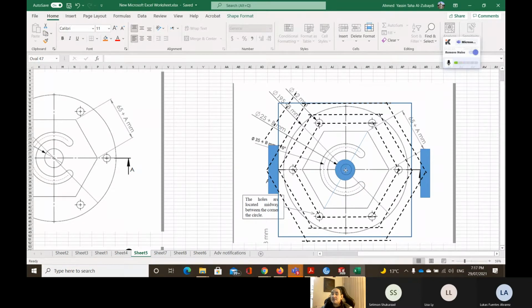Travel with G00 to X0, Y0, and Z equal to 5. Then you go G01 to the depth of the slot. We are going to be in the middle. Then we turn to the side where the center of my cutting tool will be on this circle. Then we make a 180-degree cut, and another 180-degree cut, to cut a circle shape, which is going to be the pocket here.